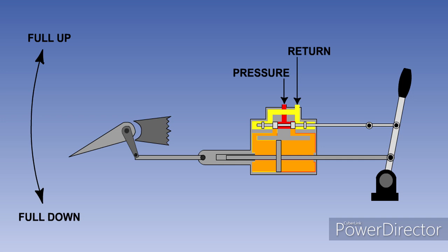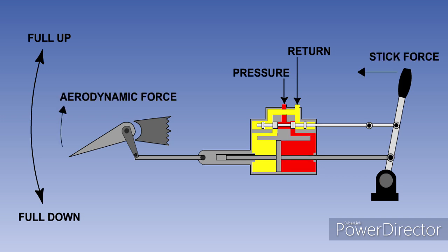As the actuator housing moves, it gradually repositions the actuator ports in relation to the servo valve pistons until the fluid is shut off and movement stops. Control surface movement is therefore amplified in proportion to the pilot's control input. In this system, the pilot is still feeling the aerodynamic loads on the control surface and must hold the control in position to oppose them.